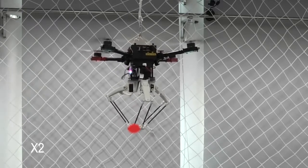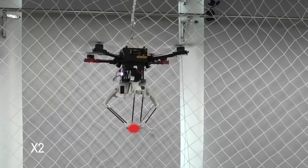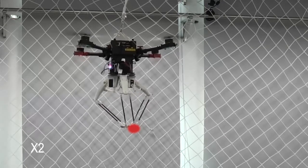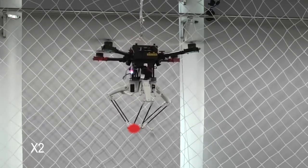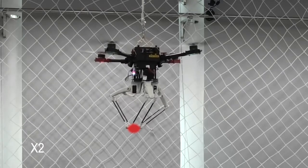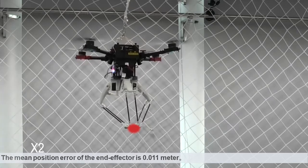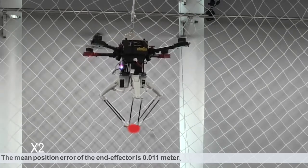This scenario considered in this experiment is important because practical tasks may require to assign separate trajectories for the quadcopter base and the end-effector. For example, the end-effector must track a desired trajectory to complete a manipulating task, whereas the quadcopter base must move to avoid obstacles or observe the manipulating target from different angles using onboard cameras. The mean position error of the end-effector is 0.011 meter.